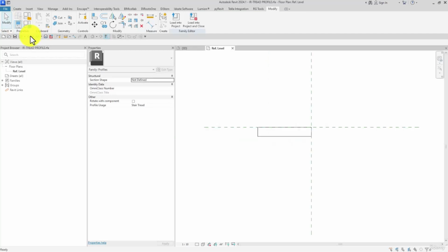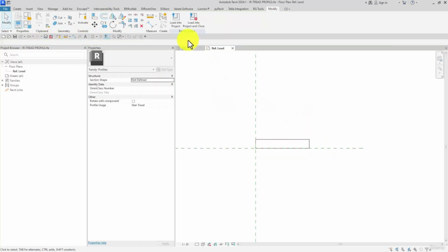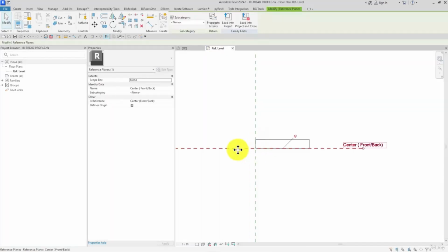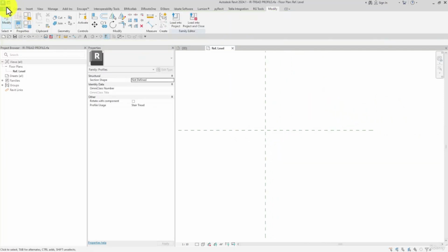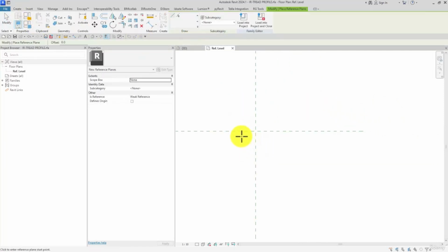Check this out, Control Z. I forgot to tell you something. Here if I mirror this at the upper part, then this is the result, and still the bottom part is empty. So you have to position the model below the horizontal reference plane.